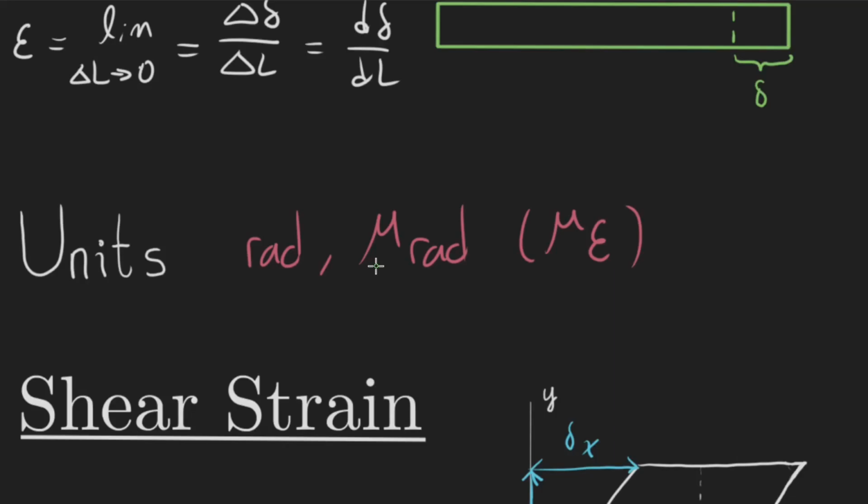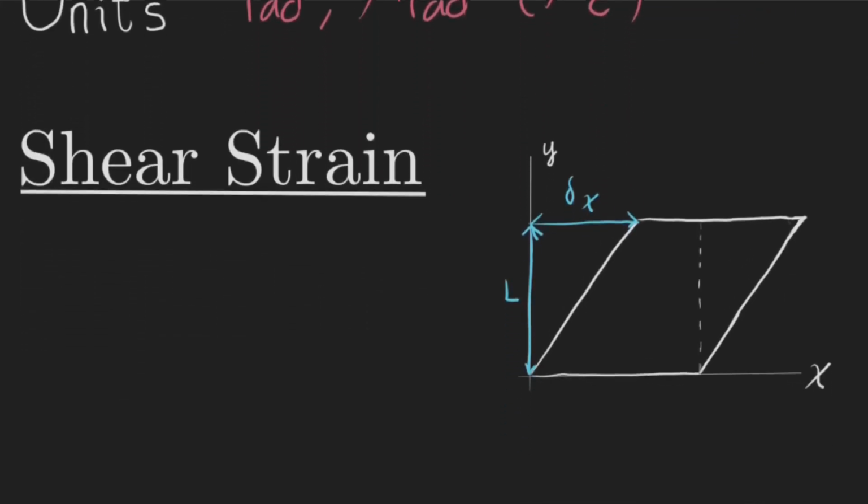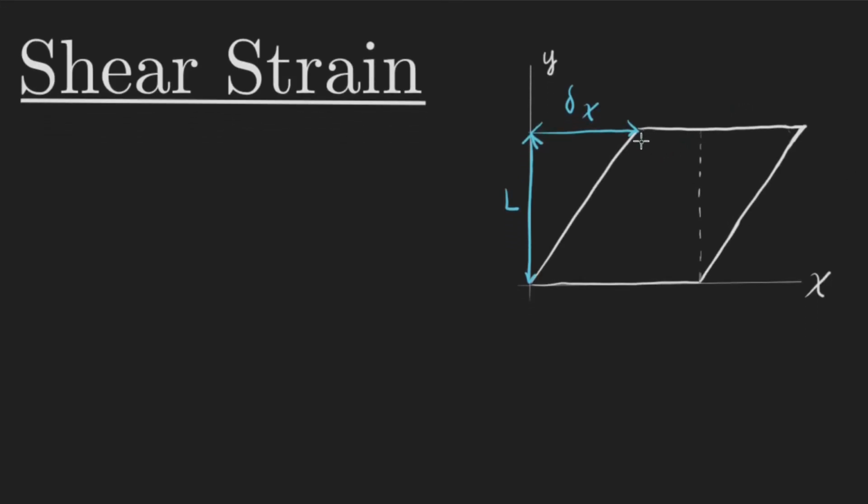And so now we can talk about the shear strain, since that was the normal strain. If we have a shearing of our object, if you imagine I take my square originally right here and then I shear it, I'm going to have my original length, and then my delta is going to be perpendicular in the shear direction, right? So my average shear, we use gamma. The average shear is going to equal, again, delta, and we'll say delta x over L, and then you could take the limit with this, right?